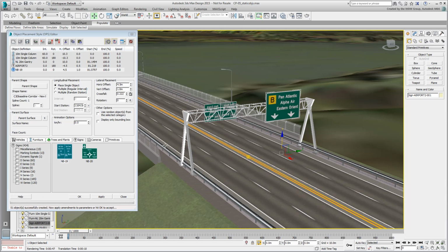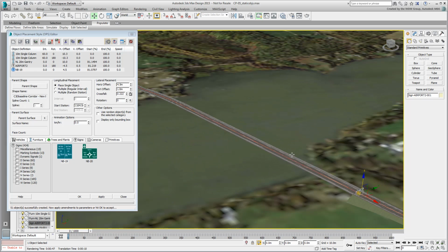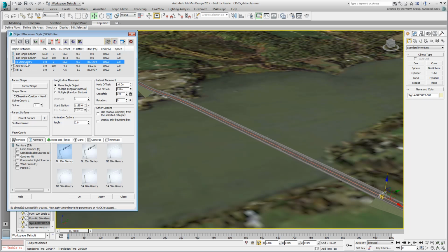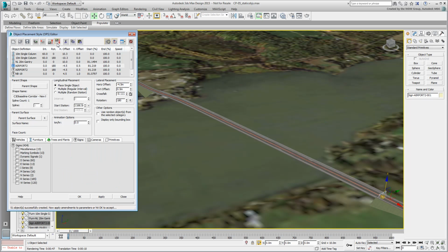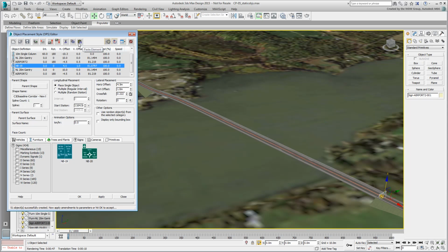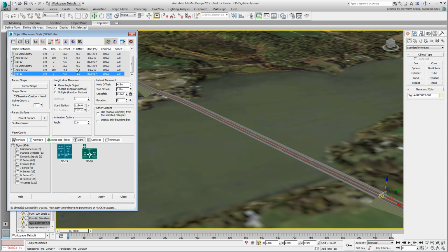You still need a gantry on the other side of the bridge. Simply copy the last three elements and place the duplicates in the same order at the bottom of the list. The only adjustments you need to make relate to the start stations.